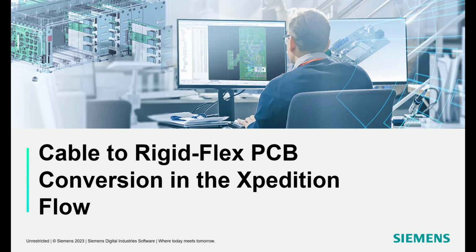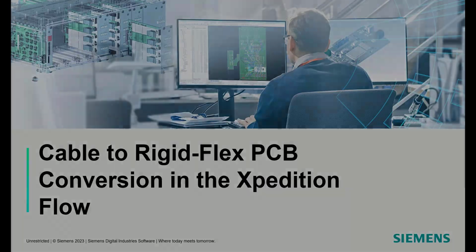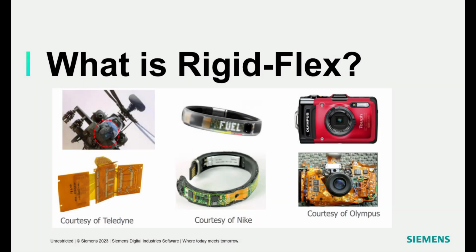routing. The cable being substituted with the rigid flex solution in this demo is designed to connect the system controller board to 3D sub-connectors found on the EBSD chassis. A rigid flex solution is defined as a single PCB design, a mix of rigid boards and interconnected flex substrates of different stack-ups, all manufactured on a single panel.